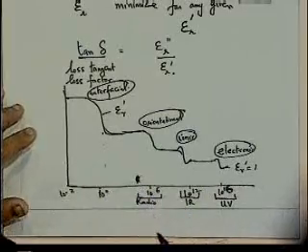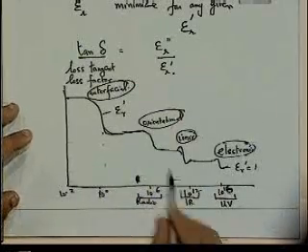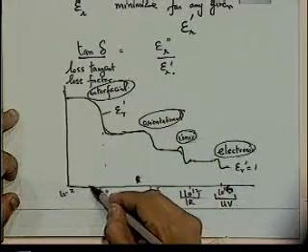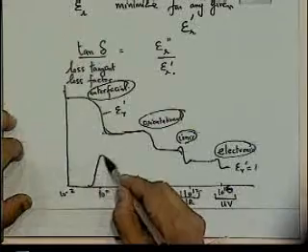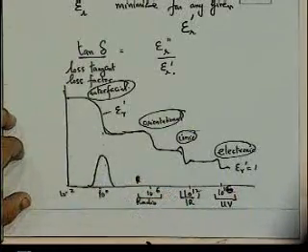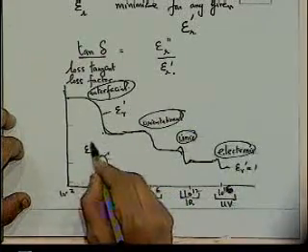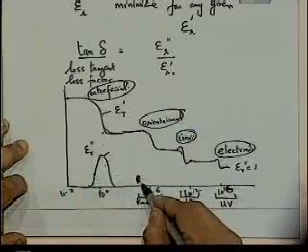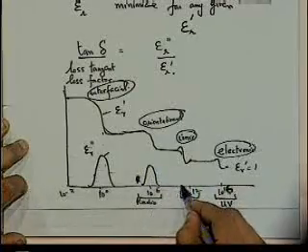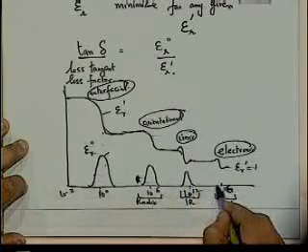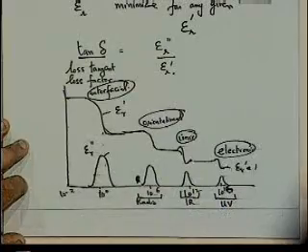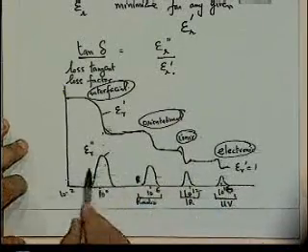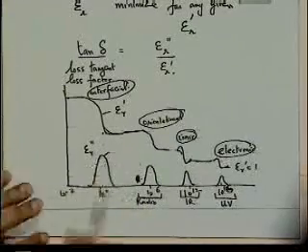Now in the same plot, we can also plot the epsilon r double prime, which is the loss component. And what is seen is that very close to these drops there, we get peaks like this. So what we're plotting here on the same plot is epsilon r double prime. And around these values, we will get peaks, and then they drop off. Okay? So the losses are maximum for each of these at some particular frequency over here.